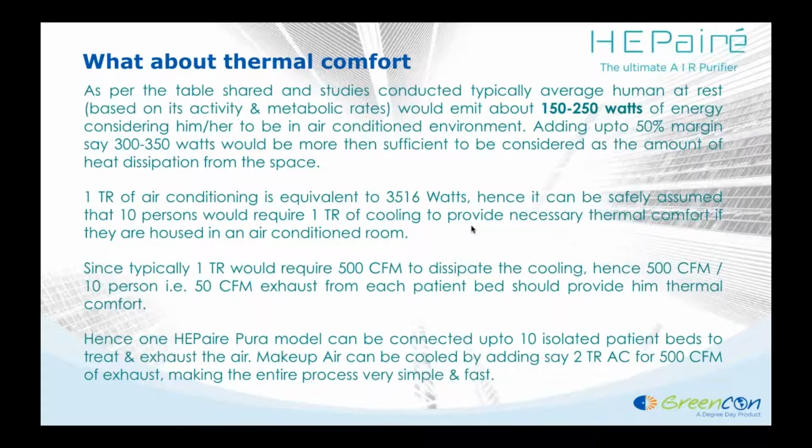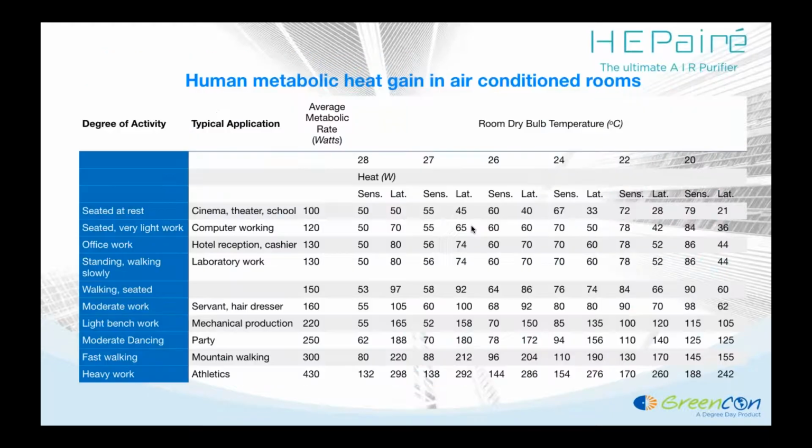Okay, so sir, unfortunately, across the globe, filters are not meant to be cleaned. They are designed to be changed when they get choked. Now the scenario, as you would understand, I've shown how filtration happens. It's not only because of sieving. The moment you wash it or clean it, the entire geometry inside the filter gets changed.